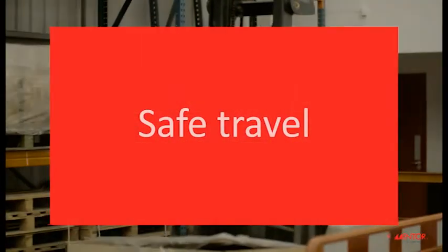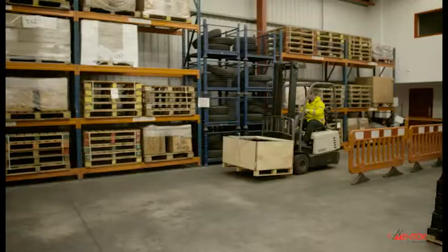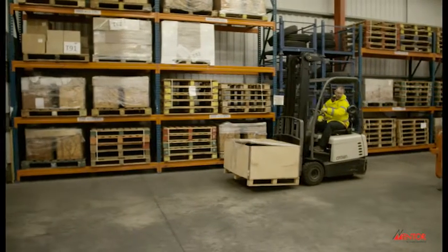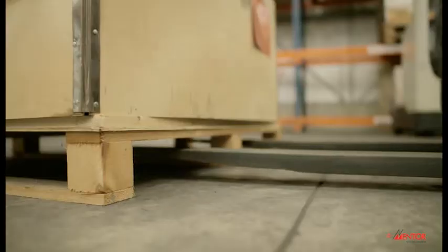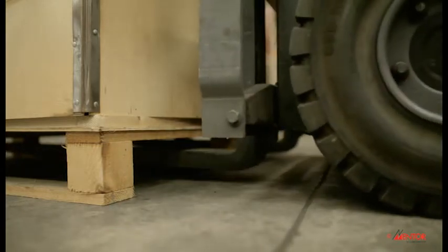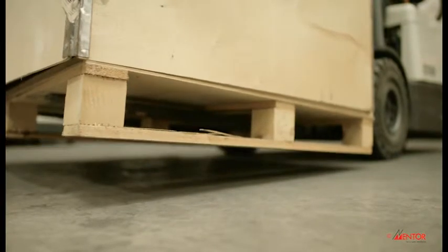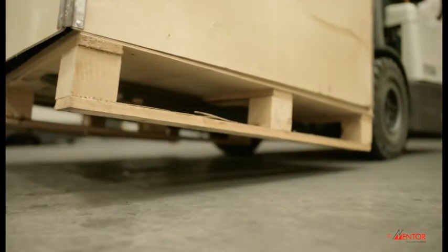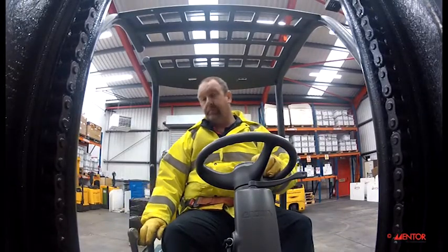Any lift truck is at its most stable when being driven at a sensible speed, on even ground, in a straight line, with a load being carried as low as practically possible, the pallet in contact with the fork heels, and stabilising back tilt applied. This ensures that the centre of gravity is as far back as possible. On a reach truck, the reach should be fully retracted to enable this to be achieved.